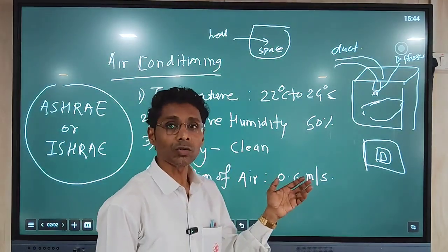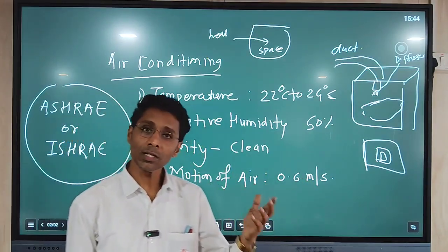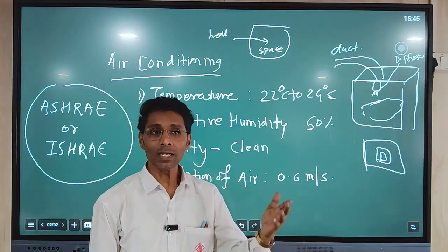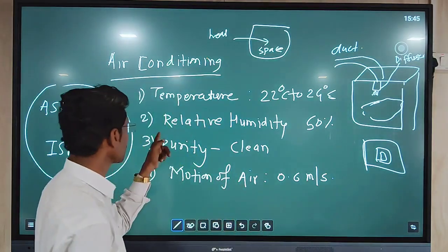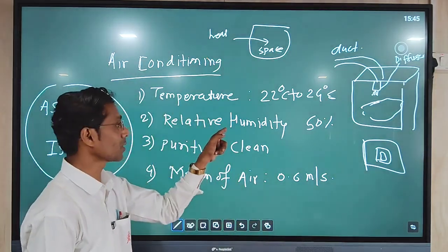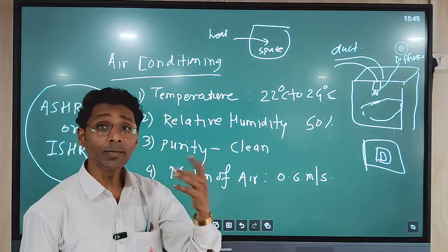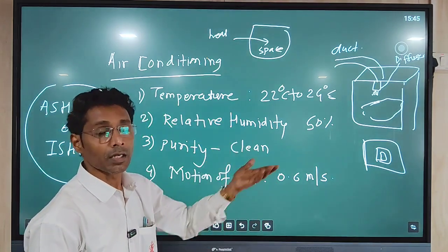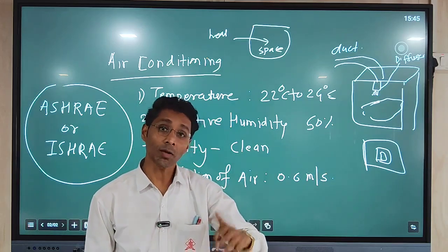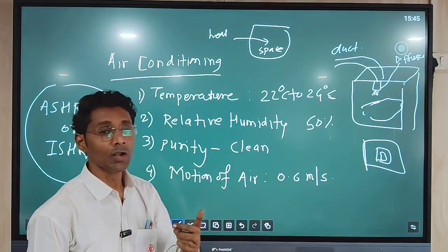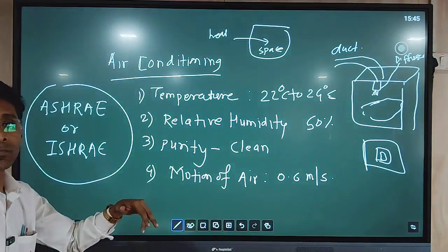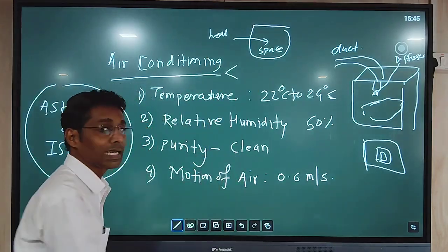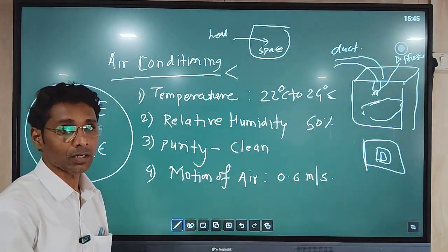And in a hot zone, for air conditioning we need to cool the air. The process carried out is cooling. Now in detail, cooling and heating are not sufficient. We have to control relative humidity. So for that purpose the process is humidification, addition of moisture to the air. Deletion of moisture means reduction of moisture from the air, that is called dehumidification. So in actual case in air conditioning the process is a combination of cooling, heating, humidification and dehumidification.